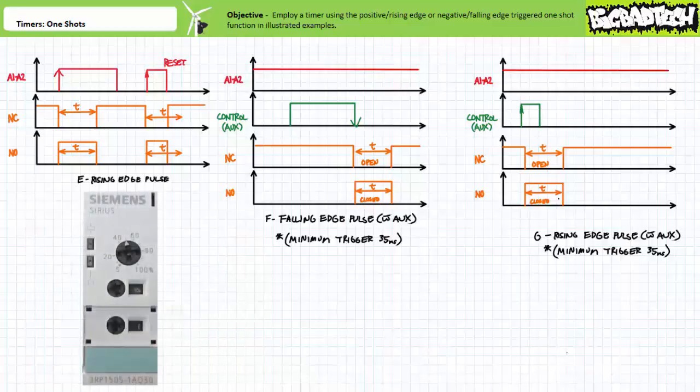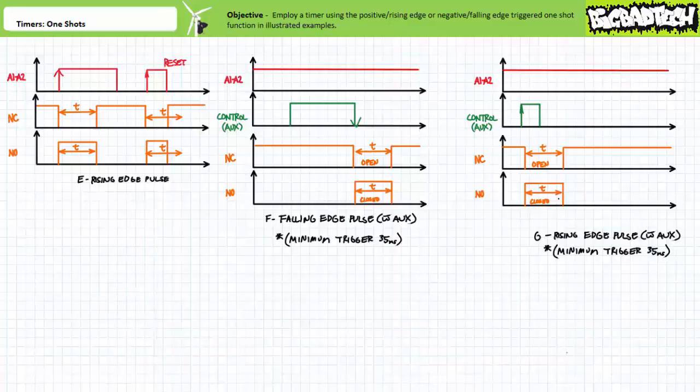You know you set up the rising edge pulse function E correctly if you energize the coil and see the output immediately change states. Wait 5 seconds for the one-shot period to elapse and see the output return to the deactivated state. Again, if I turned off the coil during the ongoing 5-second one-shot, this particular function would be immediately reset.